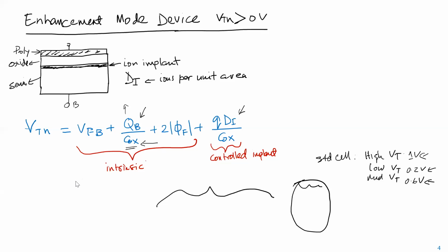So the leakage I understood is between the poly and the channel, so the capacitance becomes leaky in an LVT and not in an HVT. Actually, the leakage I was talking about is drain to source, not the oxide. So what happens is, if you have, let's say, a VT of 0.2 volts, then when VGS is zero, it's never completely off. It is always leaking a little bit.